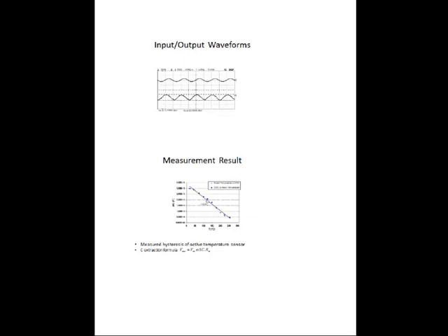So based on this, for certain temperatures we applied this, and then we recorded our measurement, and actually we went back to be able to see if there's any hysteresis, and the result was about 1 femtofarad variation per degree, which is what we expected.